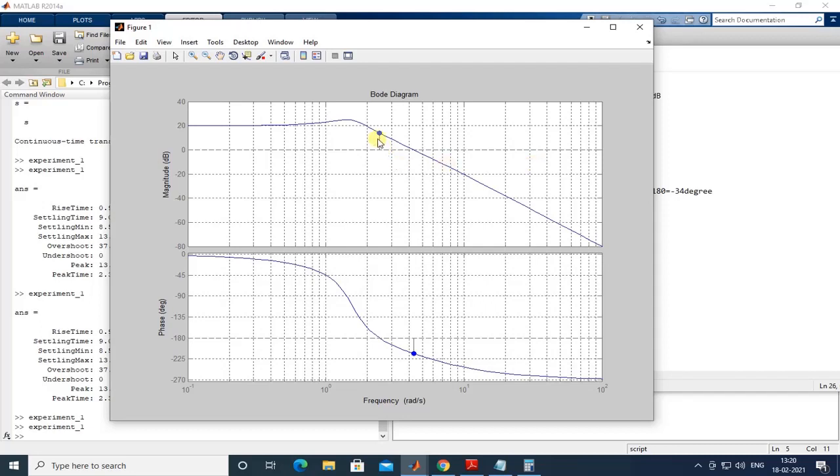Okay, now this is the gain, and the gain margin you can find over here. See, it is showing minus 14. Okay, so we also found this minus 14. We chose the phase crossover frequency to be 2.44, so that it is almost exactly the same, 2.45. And let's see the gain crossover frequency. Gain crossover frequency we found 4.39, they have taken 4.36, so almost the same.